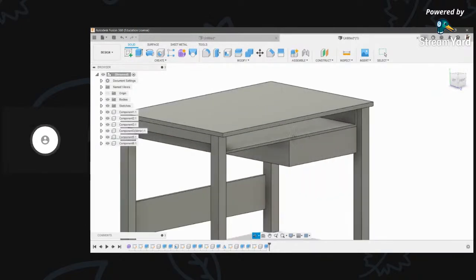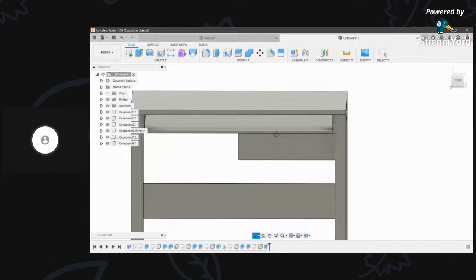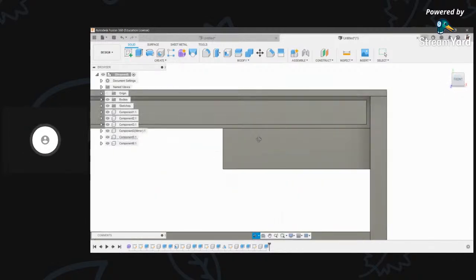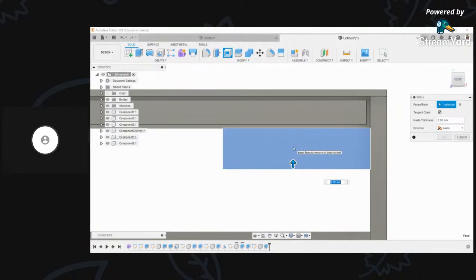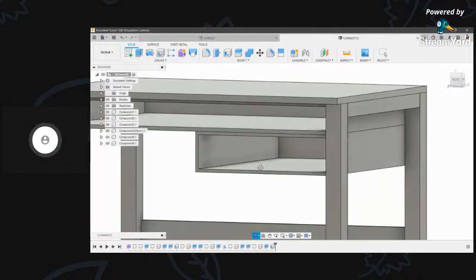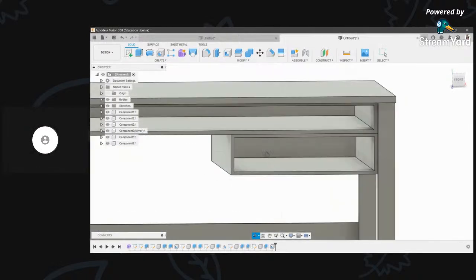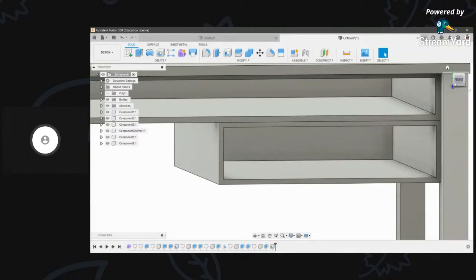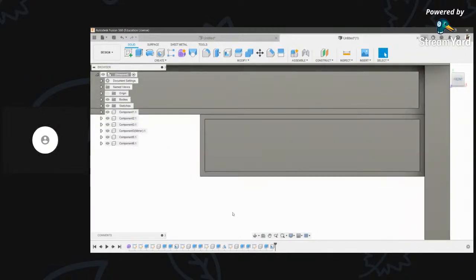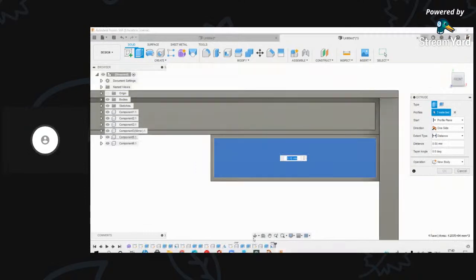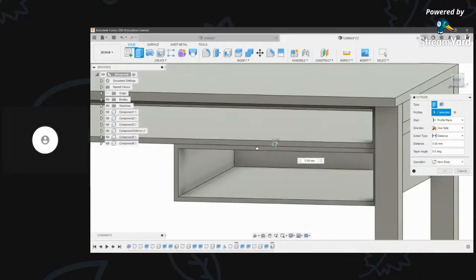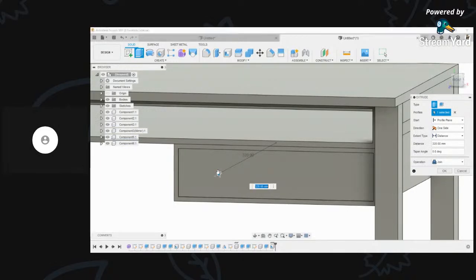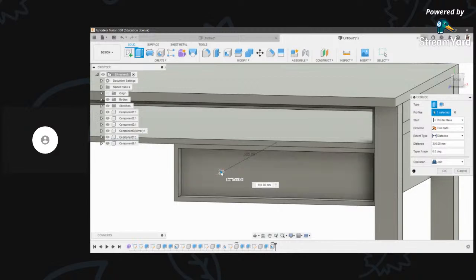So now I'll come back to my drawer part. Before that, I have to make a hole layer to insert my drawer inside. So for that, again, I'll go to shell command, give it a thickness of 5 or something. So it's the hole now. Now I'll insert my drawer. To do so, just take this back plane, which is here. Now click on extrude and click on the back plane or the line and then extrude it up to the same limit only so that you can fit your drawer inside. Wait, I'll just do 310, 35.